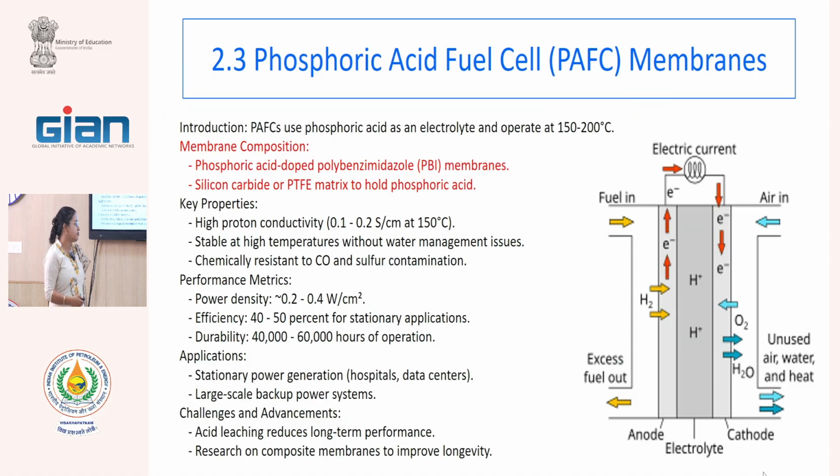The fuel is mostly hydrogen that we can give here, and it gives you higher proton conductivity than your PEM membranes. Because it is an inorganic membrane material having a lot of ions, they have a good power density, and durability is also very similar to that of the previous one, the PEM one.